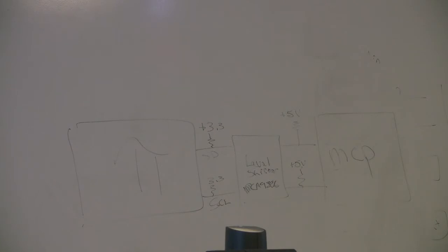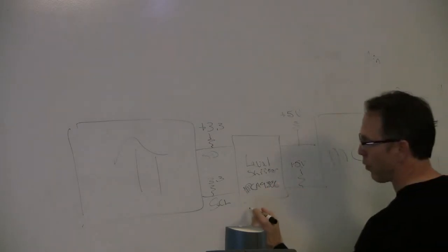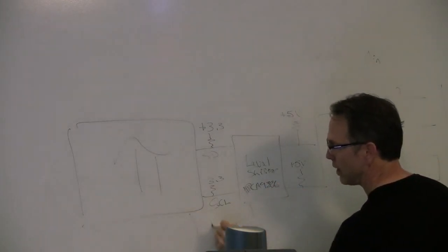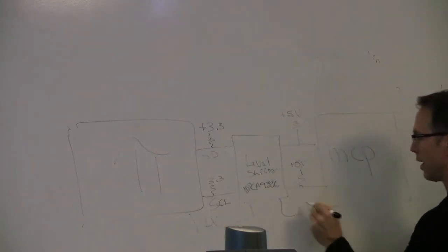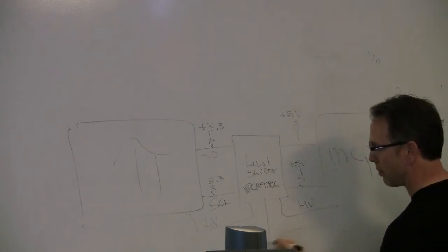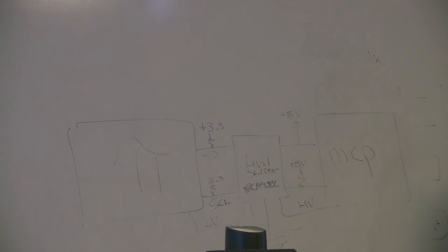Does the level shifter chip also have a VCC and a ground? It does, yeah. You usually have low voltage, high voltage and the ground. That's correct, exactly. So this thing, you make 4 connections. There's an LV section, an HV section, and then their common ground. Yeah, and that's why it's an 8-pin chip. The cool thing about it is, if the post office hasn't gotten your new chip there quick enough, the SDA and SCLs are directly across each other, so you can just lay a wire across the two, and you can continue to work on it while you're waiting for the new chip to arrive.